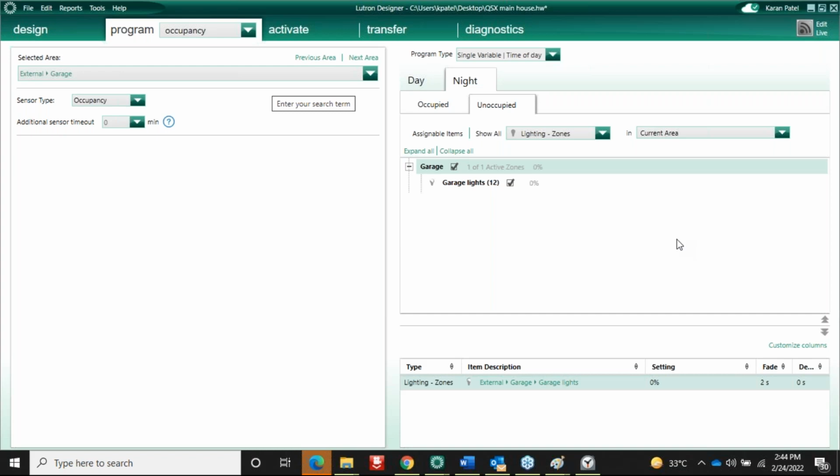In case of DALI, if it's only DALI fixtures, does the processor also require the UPS power? Ideally, the processor and the control power of the modules should always be from the UPS.